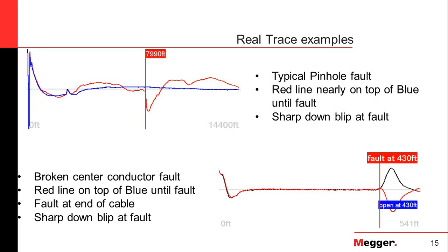And again, there's been one paper that I'm aware of where they took a radar and they were able to show that yes, we can see damage. But from a practical point of view, you can't really do it. What I mean by that is you would have to have a very high resolution TDR, and you would have to test a bunch of cables and get a good feel for what those signatures look like. Then you would have to dig all those cables up and say, all right, that signature matched this level of degradation of the neutral. So theoretically, you could do it, but from a practical point of view, you can't.